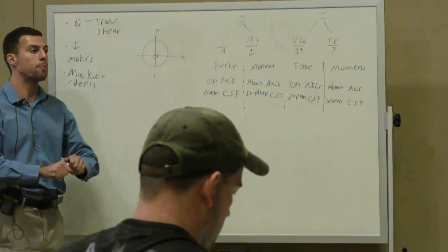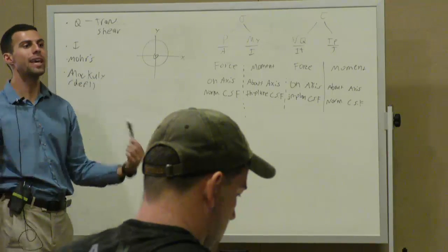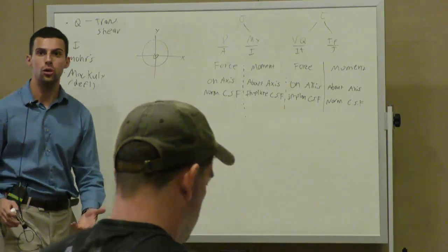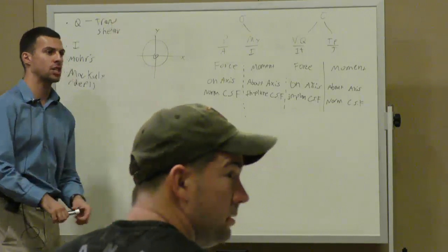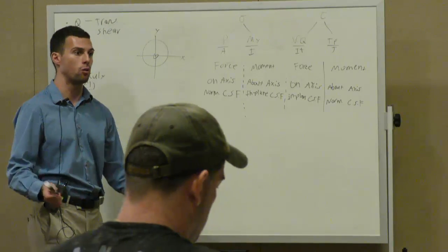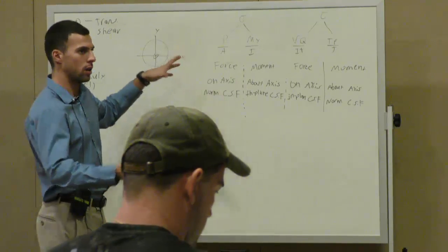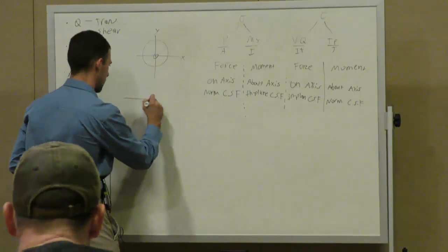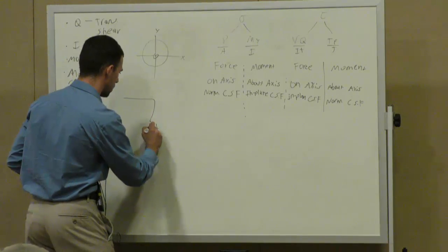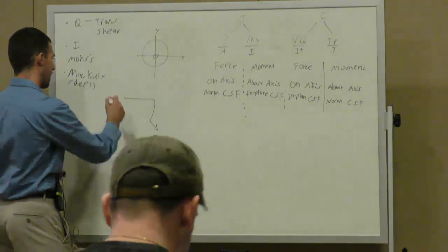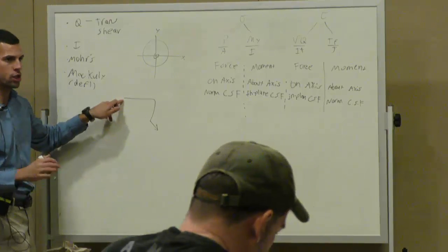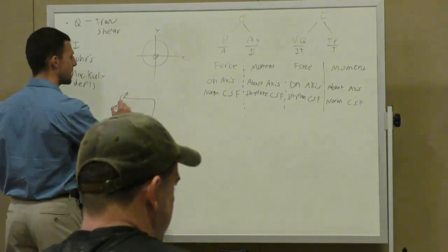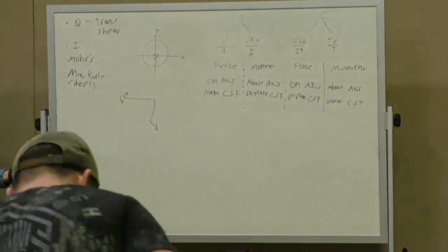These are super important, right? Because when we get to combined loading, when you do a combined loading problem, what you do is you do method of sections to establish the type of loads, right? And so, for example, if you have like a bent beam, and you have some load applied here, then you do method of sections to find out, okay, what internal stuff is happening back here, right? What moments do you have? What forces do you have, right? Everybody remembers how to do that?